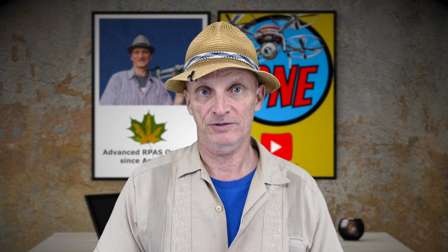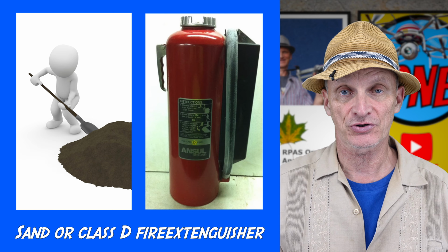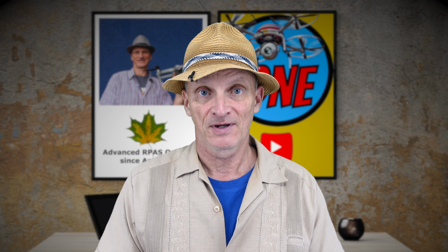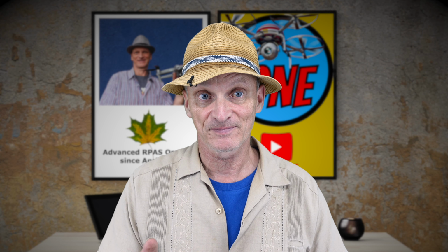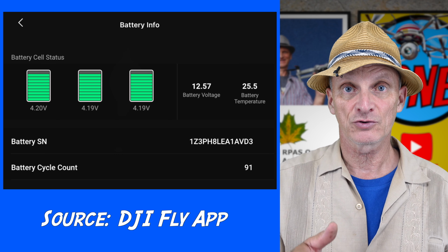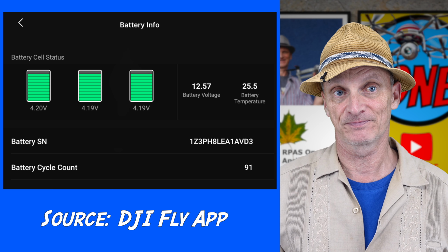If a fire starts, do not use water. Use sand, a Class D fire extinguisher, or isolate the fire until it burns out. Regular fire extinguishers may help prevent the spread, but they won't put out the fire. Most drone apps can show individual cell health. That's a good habit to check regularly.